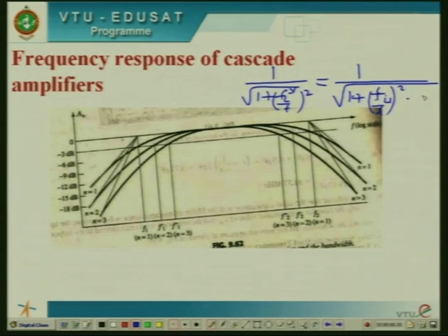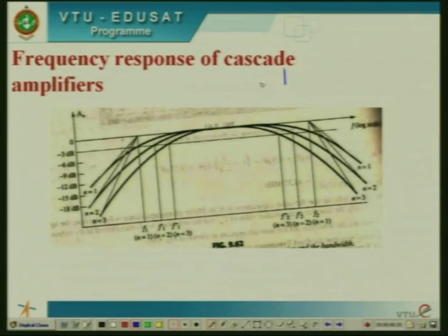For this circuit analysis, if you consider the magnitude of a circuit over frequency, then it is given by 1 divided by square root of 1 plus (FL/F) squared, at F equal to FL star, which equals 1 by root 2. If you square both sides and simplify, you get